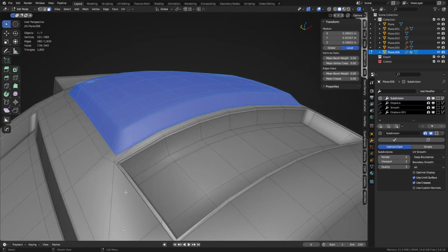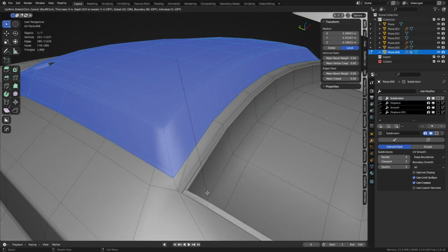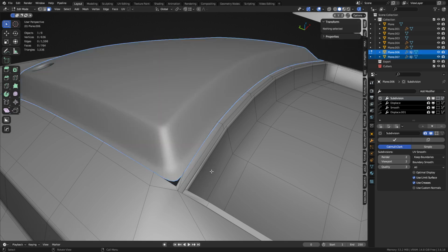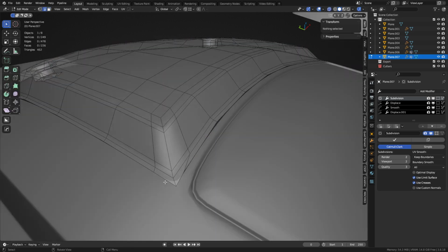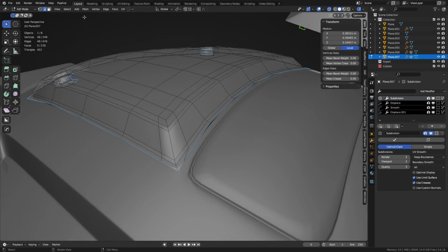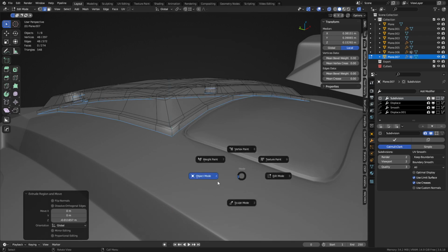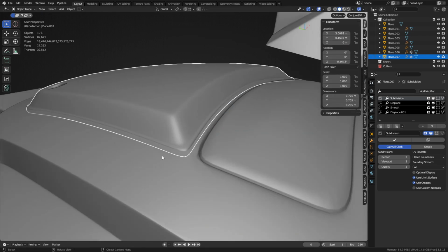Okay. You can inset, hit O, and do an outset. Select more, separate selection. Okay. Grab all of that, boundary select it. So remember, select loops, boundary loop, E and Z. That'll be our little piece now.